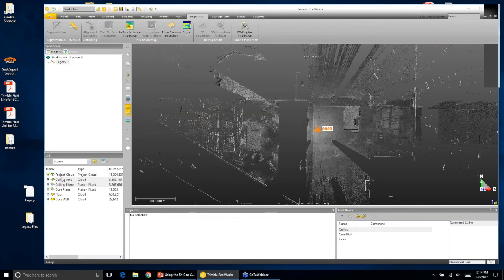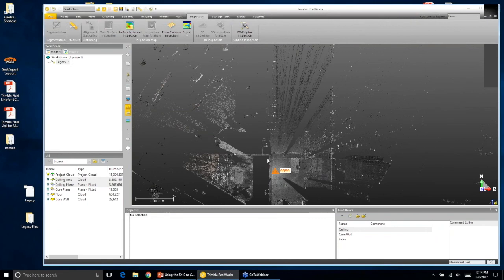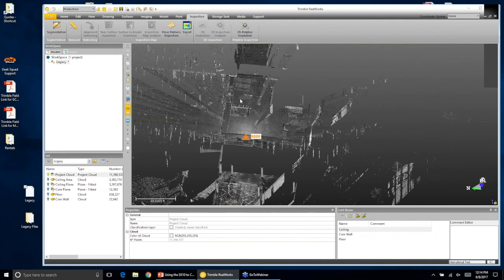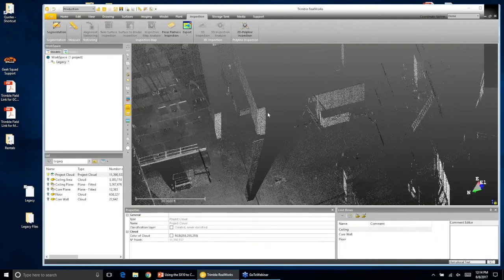Okay, so this wall right here, I already kind of touched on that this is the elevator core for the building. How do we know that this is verified going straight up and doesn't have some type of a bulge to it, or that it is truly going plumb? A lot of these things are slip formed or lift and slip when they're installed. So concrete gets poured into molds and then cures, and then they lift the whole apparatus up. If that doesn't go up true, you're going to have an issue with your structure at some point.